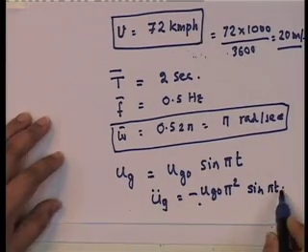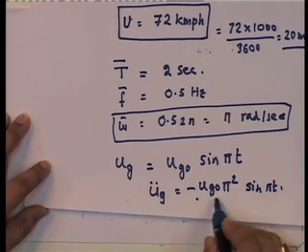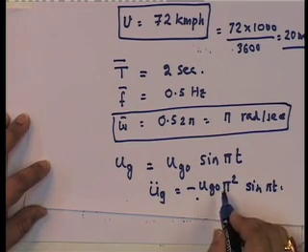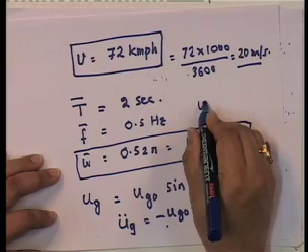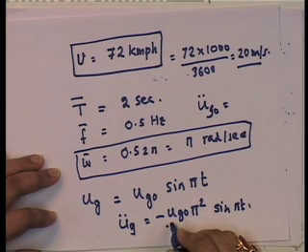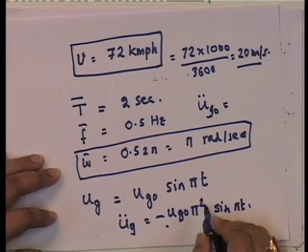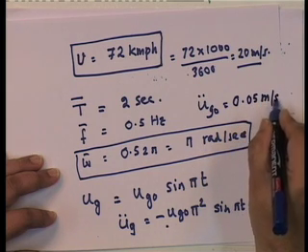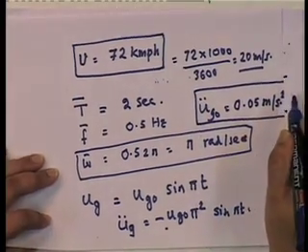The pi squared is because you double differentiate it. So, this then becomes my, and this is 5 millimeter. So, 5 millimeter becomes 5 into 10 to the power of minus 3 meters. This is approximately 10. So, u double dot z 0 is equal to 0.05 meters per second squared. This is the amplitude of my acceleration.